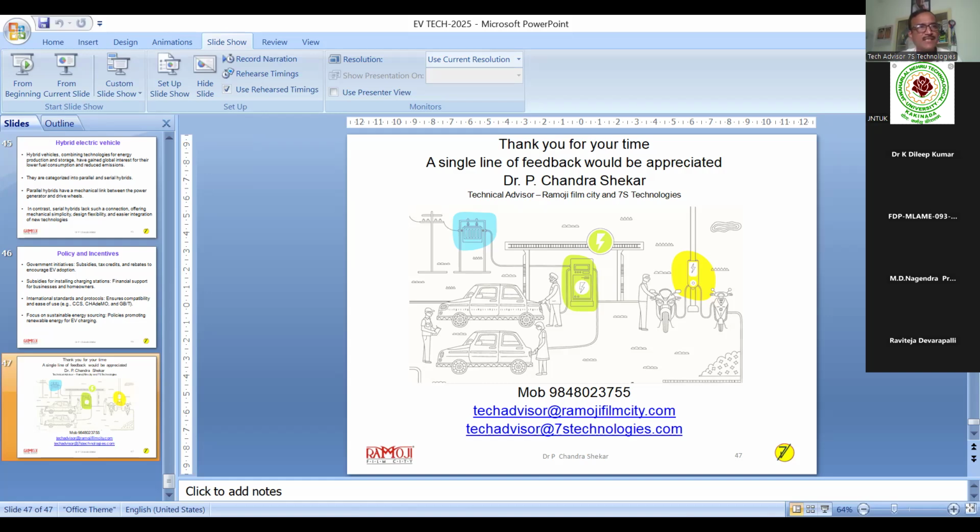And initially, when the EV vehicles came, most of the time the batteries were in the back seat. The combustion engine's gearbox used to occupy more space. Now, in between the seats, we have a space. So to avoid thermal management issues, and also to avoid water entering these batteries, they layered them over the total cabin floor area. In the front, we cannot change it like a combustion engine; we cannot take it away and make it flat.